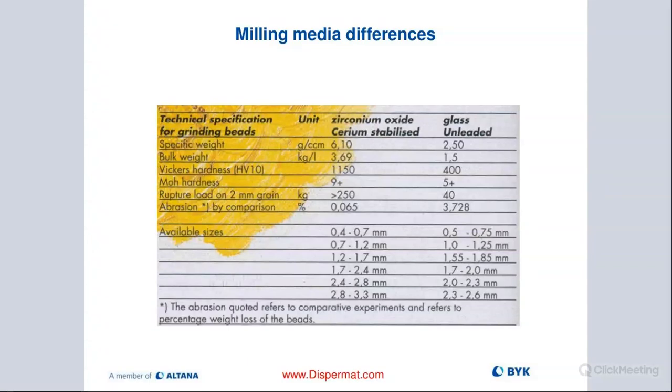So you're going to have contamination in your mill base. They wear very unevenly since they're not as hard. So then you will have an issue with breakage, you will have contamination in your mill base, and you're going to have uneven beads, which will also result in uneven milling results, uneven milling performance.